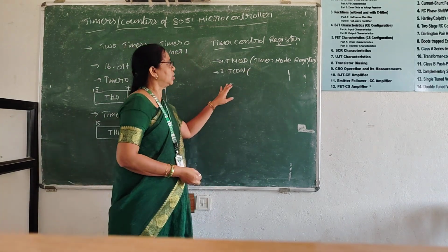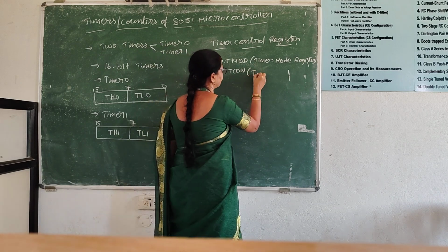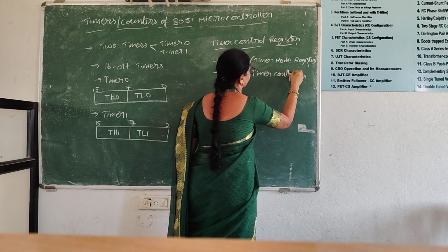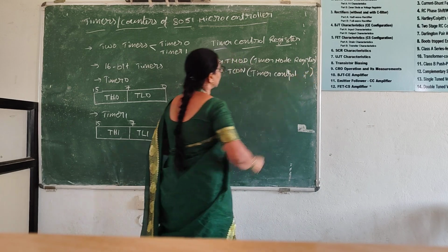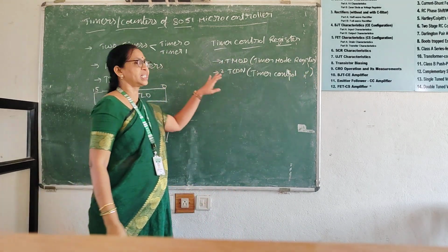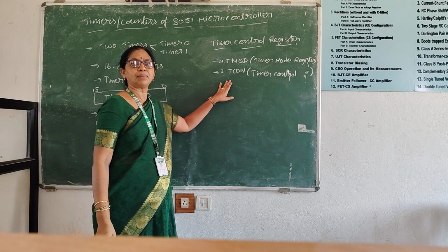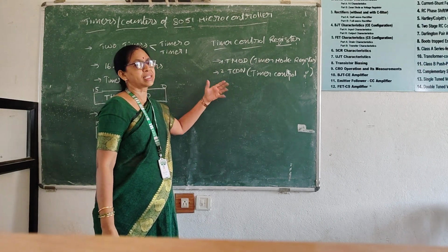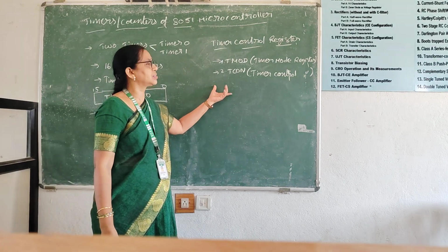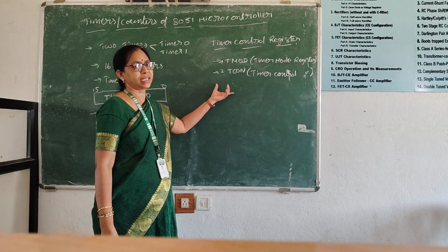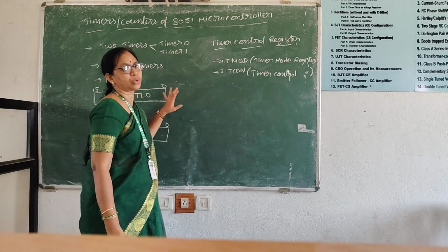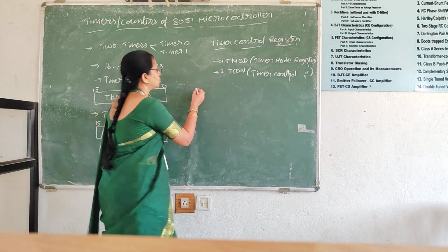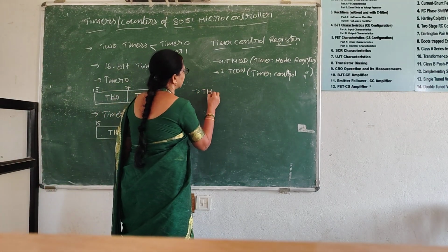TCON means timer control register. By using this TCON register, any one of the timers can be run, and some flags will be there. The flags will be set or reset depending on the overflow of the timer register or counter register. So let me discuss about the TMOD.